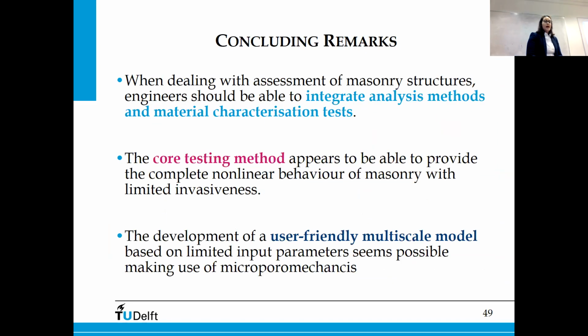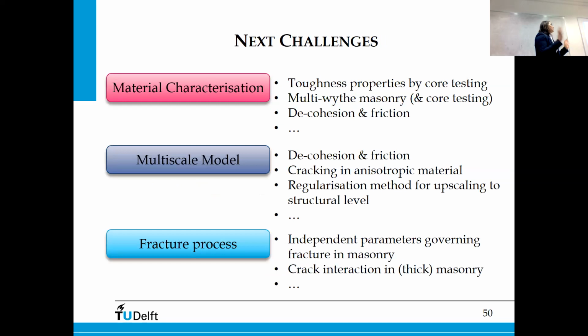So this is what we are working towards, to develop this integrated way to have an analysis method that can interface with material characterization tests. On one side, we are trying to use a core testing method to provide the complete nonlinear behavior of the masonry with limited invasiveness. And on the other side, we are trying to develop a user-friendly multi-scale model that can work with just limited input parameters. Of course, there is much yet to be done before reaching there.